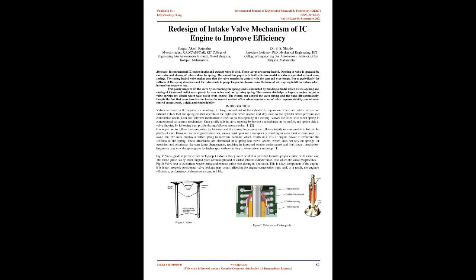The cam profile aids in valve opening by having a raised area on its profile, and the spring aids in valve shutting by following the cam profile during the follower return stroke. It is important for the follower to follow the cam profile, and the spring force presses the follower tightly on the cam profile to follow the profile of the cam.